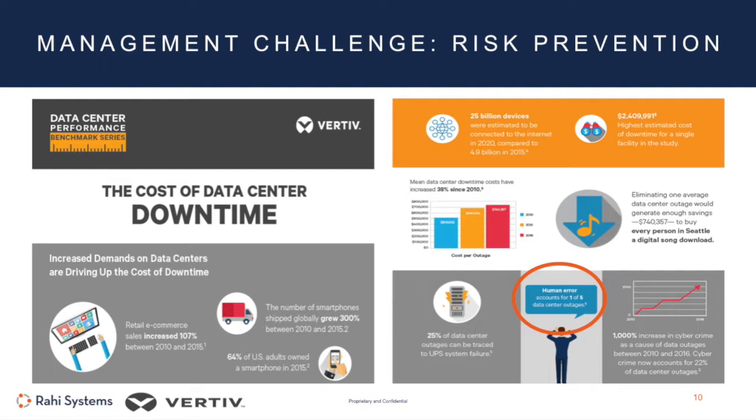And if those colors are repeated throughout the power chain as they go upstream from the facility, from the data center into distribution rooms or mechanical corridors or battery rooms, etc., I think the better chance that operator will have of success to prevent this type of outage that would be related to power feeds, etc.